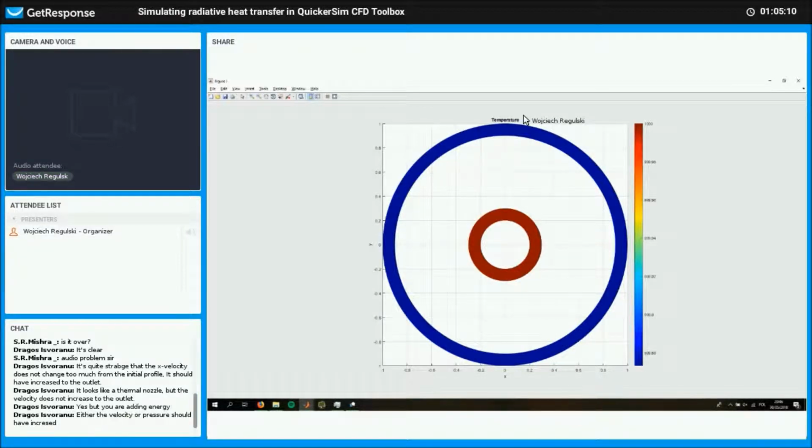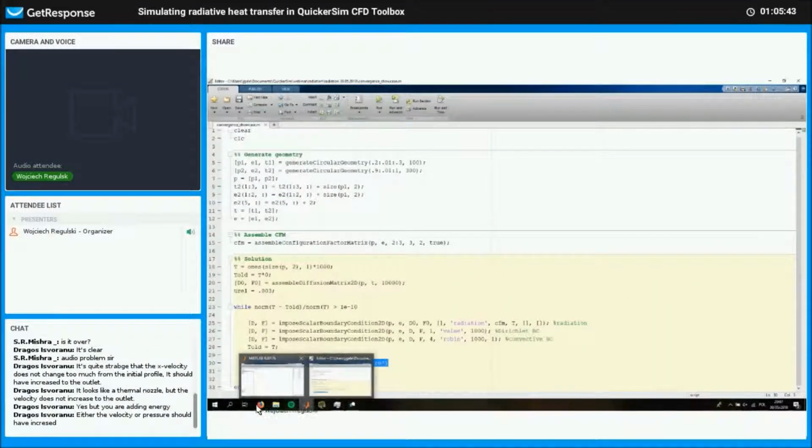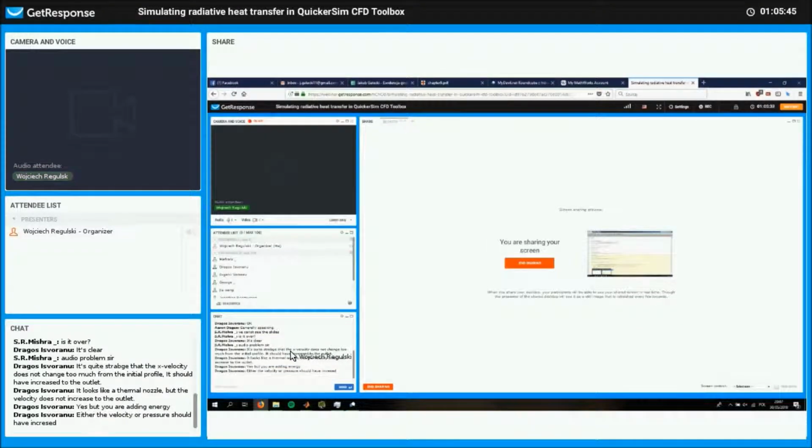was in the area of 900, and we needed to employ an under relaxation factor of like 0.2, which for fluid flow is fairly small. For radiation, actually, it's fairly large. I've worked with cases that require even an under relaxation factor of like 0.05 or 0.02. It's very case dependent. The rule of thumb is to start at like 0.5, and if it doesn't converge, then try a lower one.